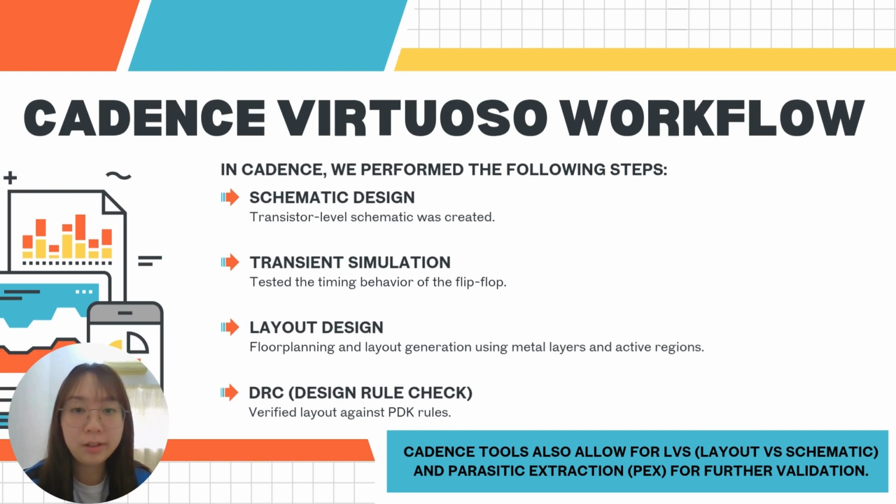Finally, we conduct the design rule checks or DRC to ensure that our layout complies with the foundry design rules. In addition, Cadence also provides tools for LVS, layout versus schematic, and PEX, parasitic extraction, to further validate our designs.